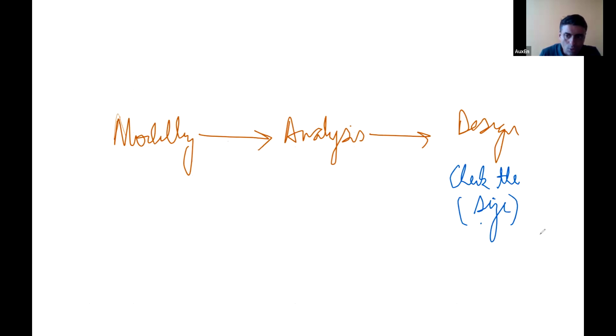A crucial problem, please understand, very important: RCDC is only taking the analysis file. Suppose I had taken a 200 by 500 beam, and then I run the analysis, and I could see that this size is not sufficient. So I could change the size to a higher size. In RCDC, you do have the features to change the size.